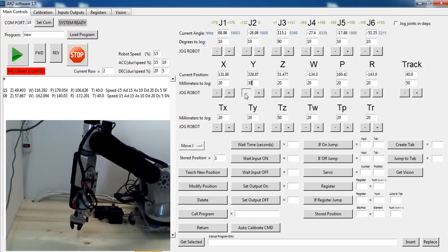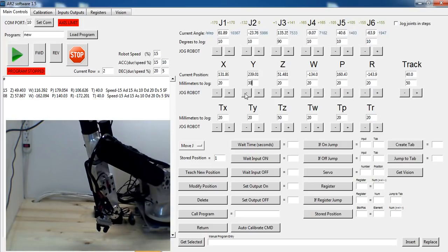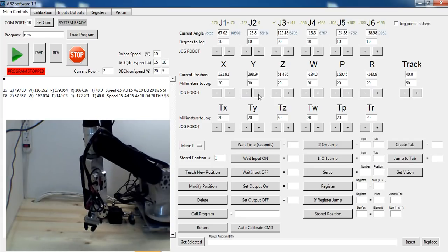Wrong way again. And then continue moving in that direction once you flip the wrist and got the wrist in the right orientation. So with industrial robots that have servos on each axis, servo motors, they have encoder feedback. I don't have encoder feedback, so I don't have any sensors to look at to tell me the wrist is about to flip and make it easier.